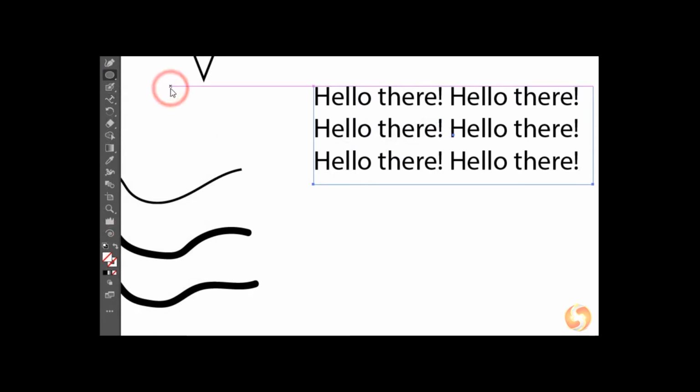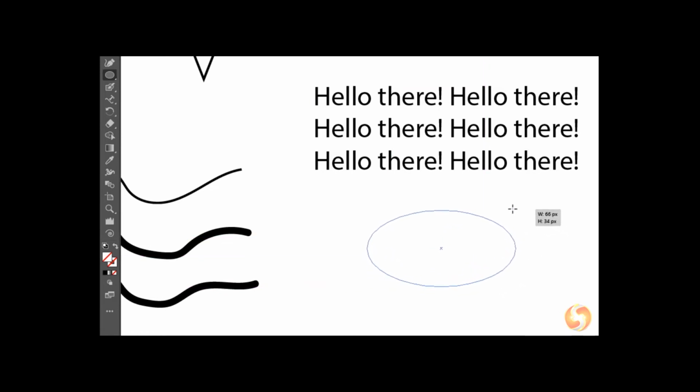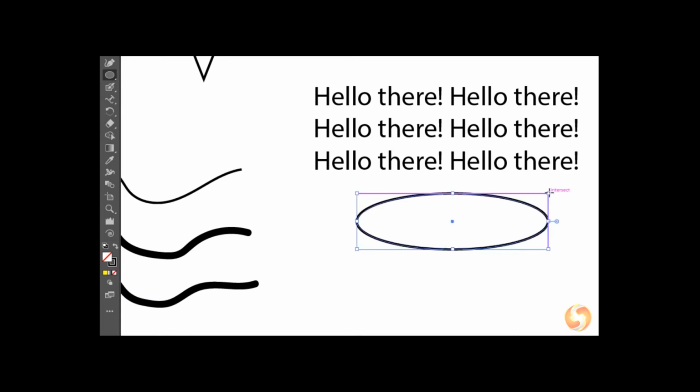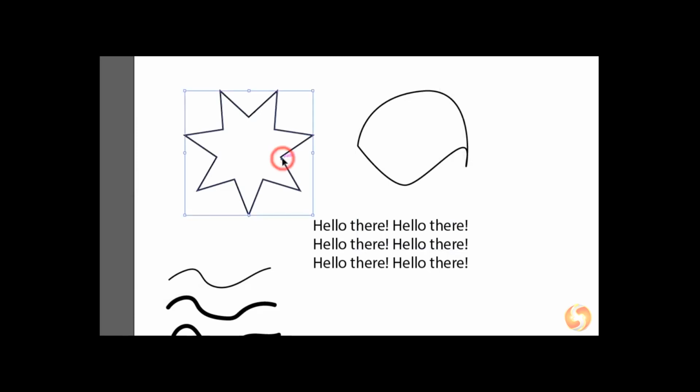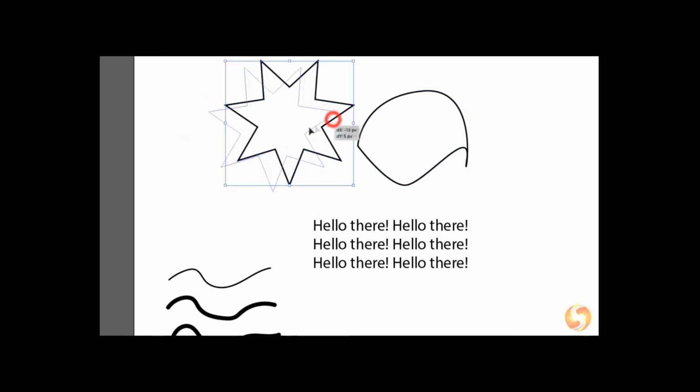Illustrator has several aids to make drawings easily. When drawing any shape, you get a small box indicating its width, height, length, and inclination in progress, and also its basic skeleton in blue color, from which the object is made with stroke and fill color. This skeleton also allows easy snappings to its object path, anchor, or directions, and can be edited to reshape the object it belongs to.